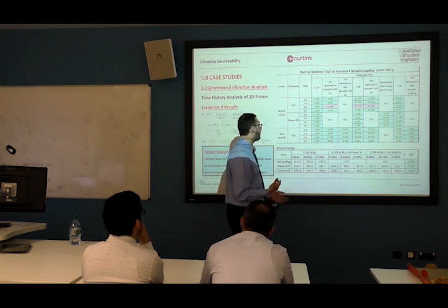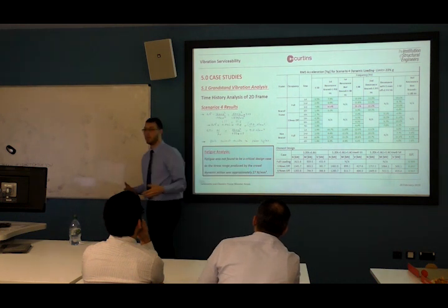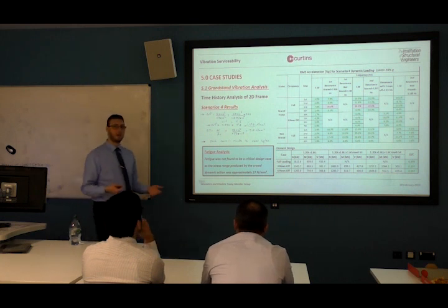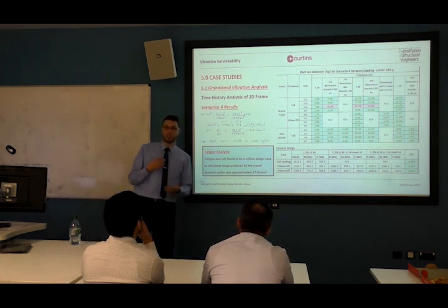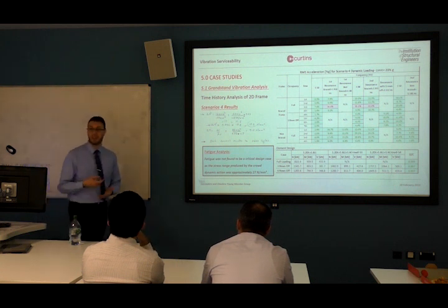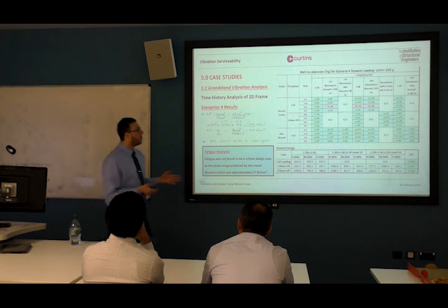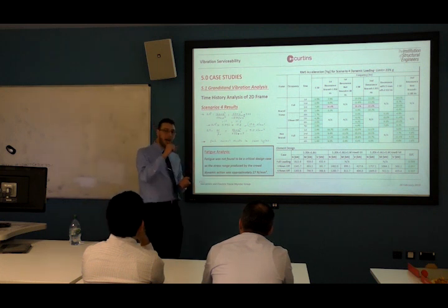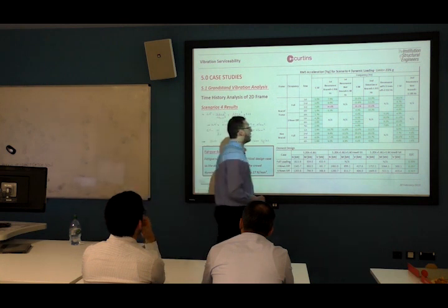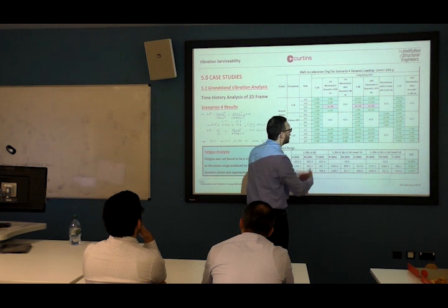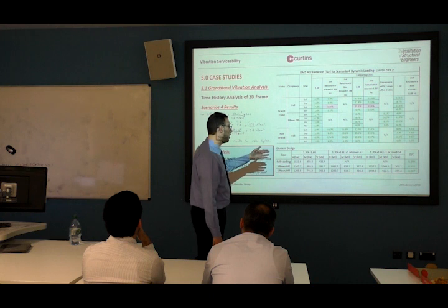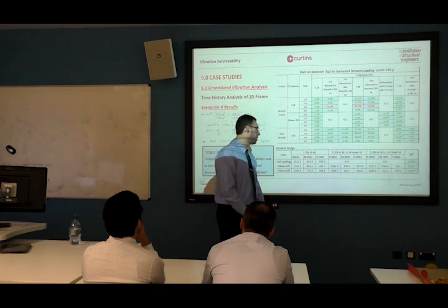You remember, we need to achieve now 20% of G. So for that video, when people were jumping, you know, singing, it's about 20% of G. 20% of G is a decent earthquake, isn't it? So what we need to achieve is 20% of G, but also the dynamic displacement cannot exceed 7 millimeter. So we had to go through the check again and check how many rows we have to net off for scenario 4 for the other concept.